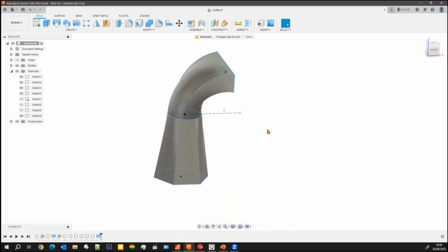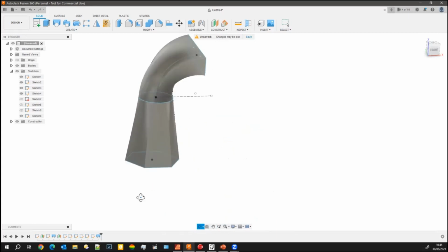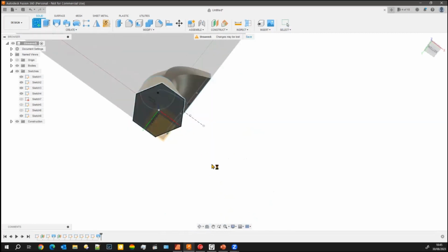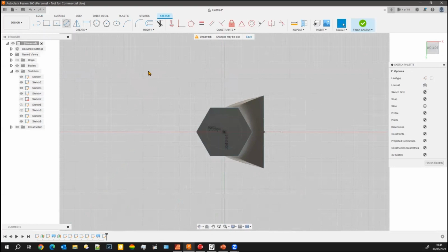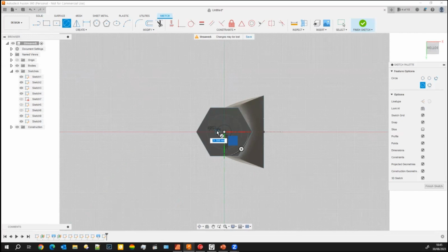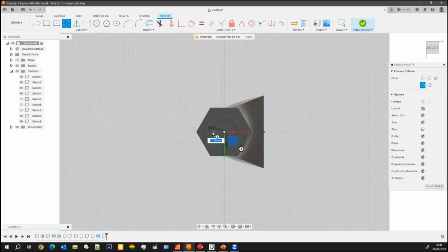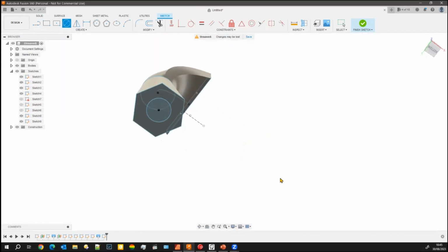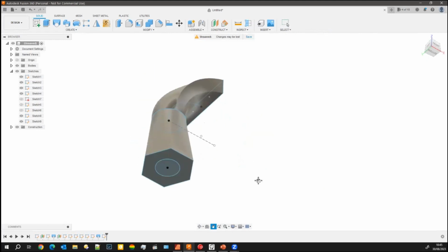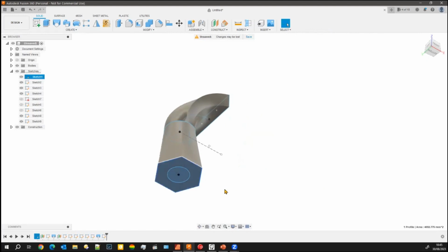Oh, it's all silent, John. So if you wanted a hole, say, going up through that, if you were making like a Hoover connection. Yeah, you could. Well, you can make the hole from the start, really. So it's a section there, and then basically, let's say we're going to put a hole in there. I'm going to make a smaller hole, otherwise you'll have to, well, let's see what happens. So there's our hole, okay? Yeah. So what we want to do now, you can extrude that one.